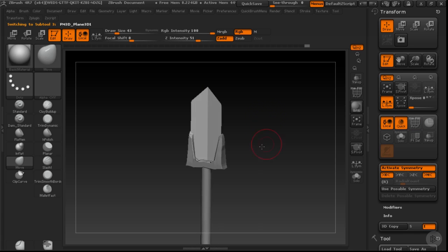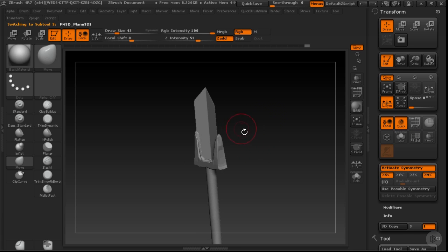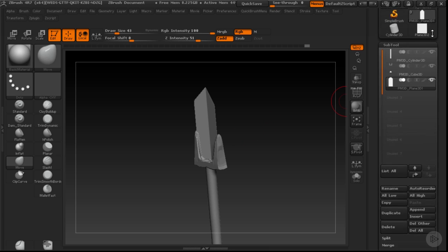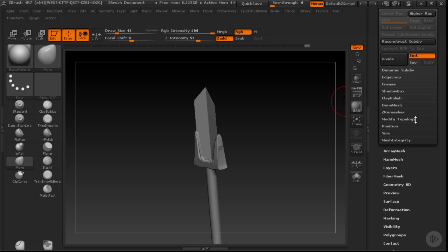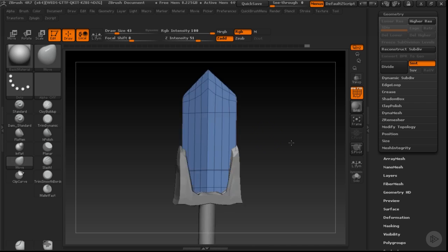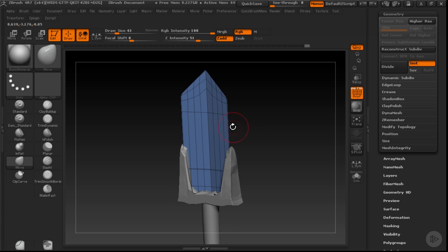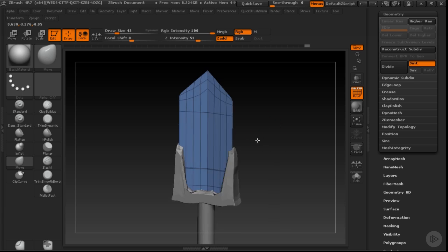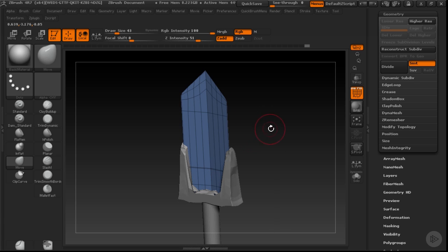I'd like to give it some dimensionality. I'd like to have some sort of thickness to it. So to do that, let's close up our transform here and scroll down into our geometry section. Now, one of the things that I think is really useful is when you're working with one of these flat pieces, like I've been working with, there's a reason for it. I like working with these flat pieces because it has no thickness to it, which means when I decide to give it thickness, that thickness will stay consistent.